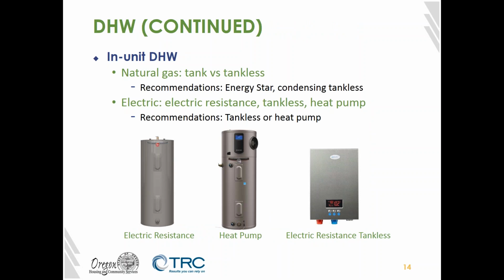For in-unit water heaters, a lot of the time you'll be running into electric resistance water heaters, and those we will recommend that you move to heat pump systems, which are somewhere in the realm of 3 times or more as efficient, for the heat pumps that you can just buy off the shelf, than a standard electric resistance heater. So it's a much more efficient system, and the only thing that you have to be aware of is it's a little bit larger than the electric resistance system, and it does use air.